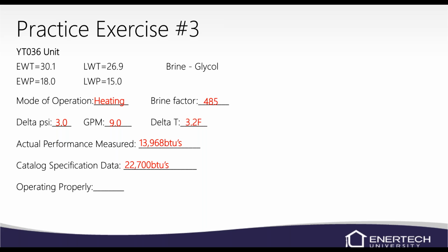In this example, I wouldn't immediately go throw my refrigerant gauges on there. This YT unit is a 2-stage unit. And in first stage, we run 67% capacity or 2/3 capacity. So the first thing I would check on this, make sure that the thermostat is calling for your second stage. If so, then check your solenoid on the compressor itself and make sure that it's staging up, that we're getting that extra 1/3 capacity. If you want to know how to check, make sure that the compressor is upstaging the second stage, amp draw is the best way to know.